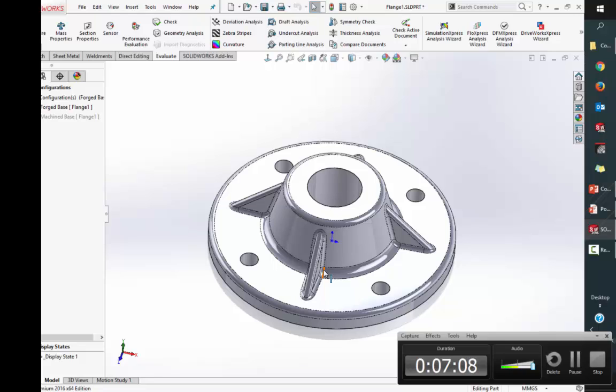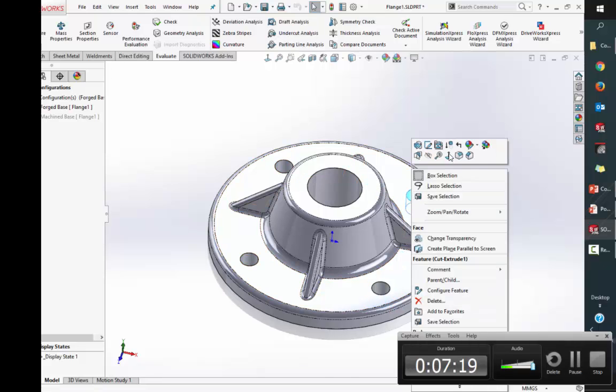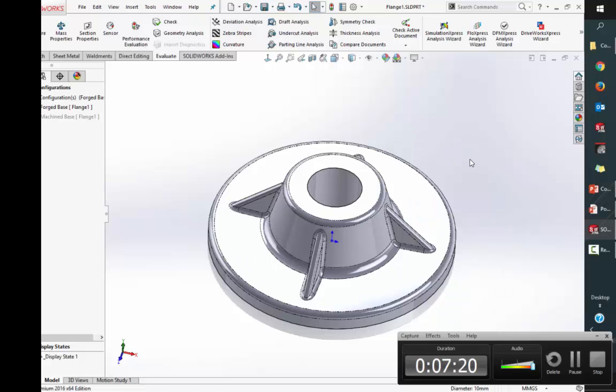I'd rather keep that as a machine operation afterwards, because I've got to have some quality and some good tolerances here. So one of the things I'll do is come through here and simply right click on one of them, and then I'll hit suppress, and that's going to go ahead and get rid of all the holes at that time.